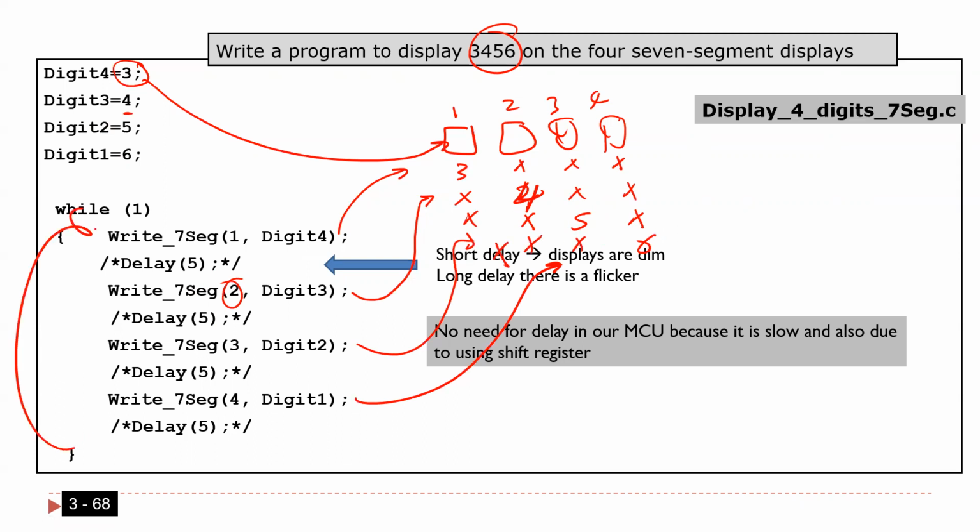And then because of the infinite loop here, you are going to keep doing it. You can see what I did? It's going to be 1 digit in display number 1, 1 digit in display number 2, 1 digit in display number 3, 1 digit in display number 4, and you have to do it fast, in a while loop. That's what we call time multiplexing.